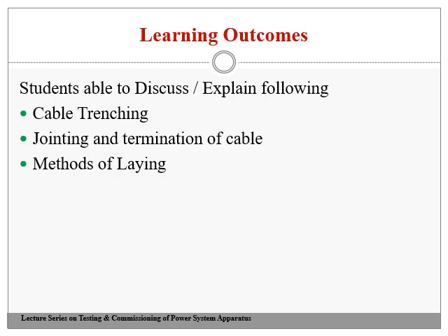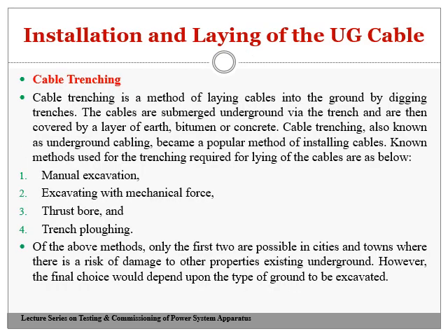Especially, much care should be taken in case of industry. Wherever the fault occurs, that part of the cable where the fault occurs should be removed, then the cable joining can be done. Now we'll go one by one.